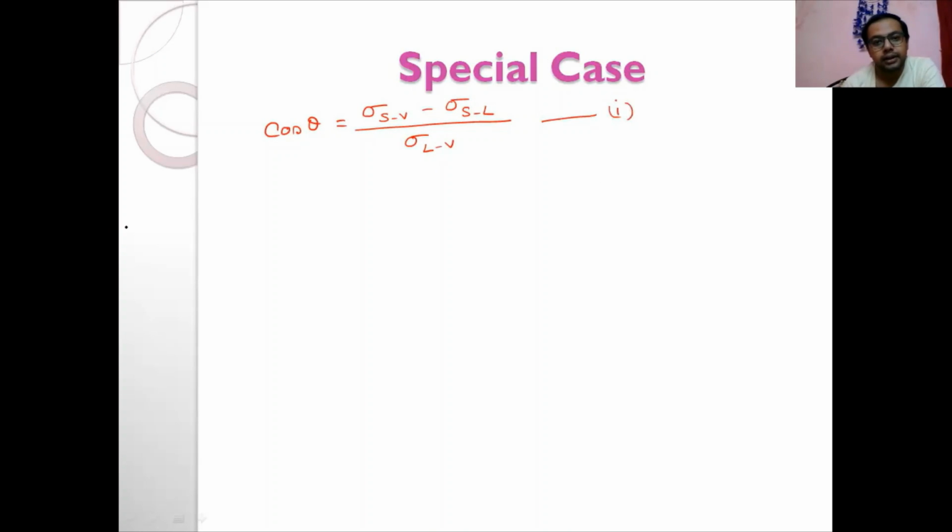The next equation, for a curved surface: delta P, the inner pressure minus the outer pressure, equals sigma into (1 by R1 plus 1 by R2), where R1 and R2 are the radii of curvature in the two portions. These two equations are necessary for equilibrium.